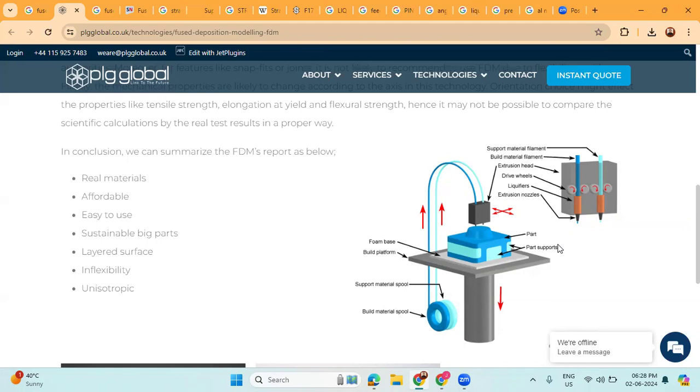The machines employed in wire additive manufacturing can be characterized by their kinematic configurations, which may include serial, parallel, or hybrid systems, each with its own implications for precision, speed, and versatility in manufacturing complex geometries. The energy sources used to melt the wire for deposition are crucial to the process and can involve various methods such as resistance heating, induction heating, arc welding, and advanced energy beams like laser or electron beams. The choice of energy source can impact the quality, speed, and material compatibility of the additive manufacturing process.